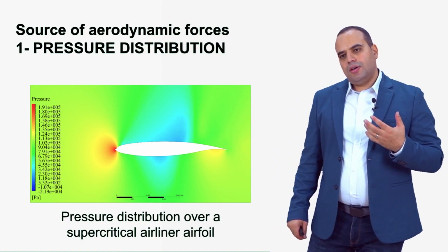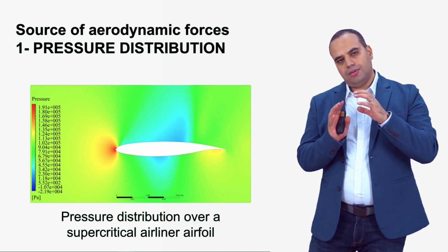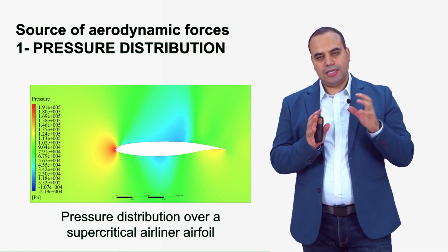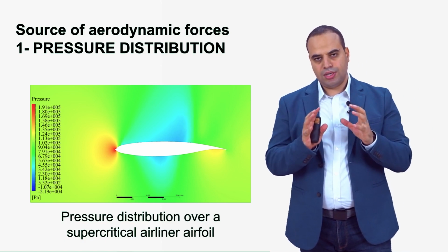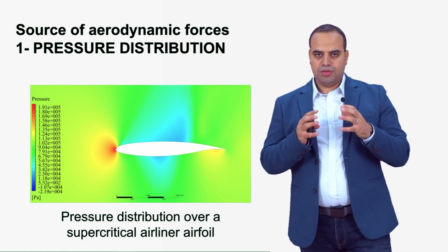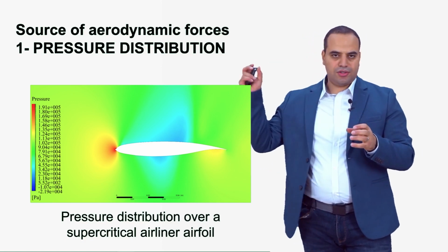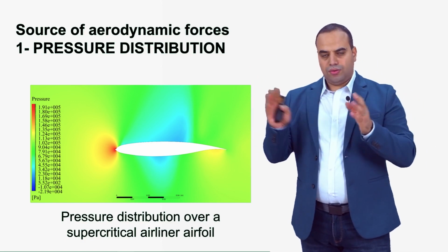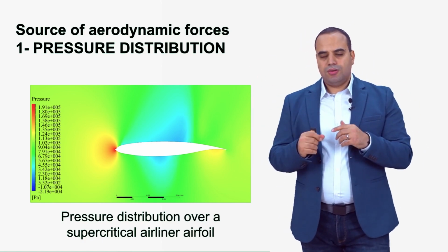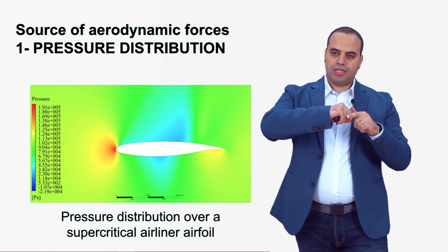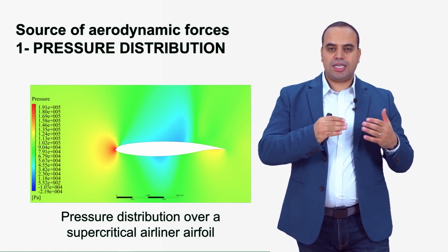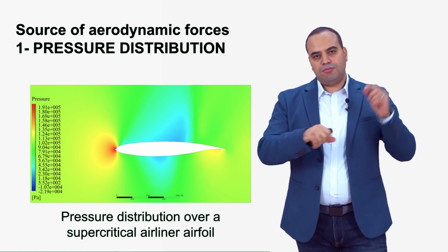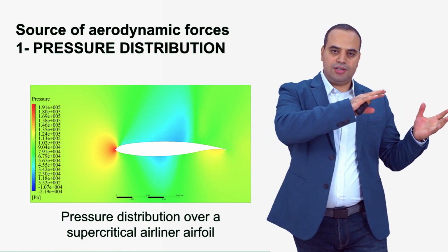Now, because of the accumulation of the particles on the leading edge of the airfoil, it creates a kind of potential energy. It's like a pressurized gas, right? It's like a pressurized balloon. If we take, for example, a balloon and create a lot of pressure inside of this balloon, and then if you remove the clamp, this gas is going to be accelerated in all other directions. And the same thing happens here, right? So although this is drag, the high pressure on the leading edge of the airfoil, although it is a bad force, it leads to accelerating the flow on the top surface of the airfoil. And when the flow accelerates, those particles, instead of bombarding the surface of the wing, start having another direction of flight, right?